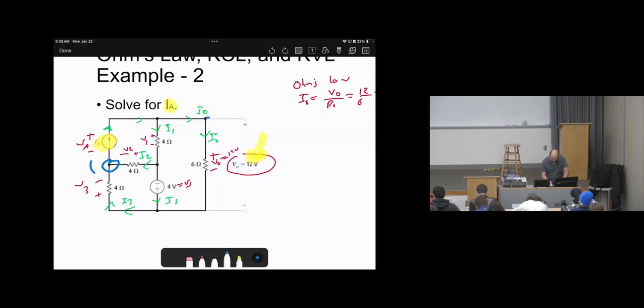Here is node 1, here is node 2. I think I messed it up. This is node 2, here is node 1. Okay. So that KVL was not a good idea. Then, how about doing KVL here? Is it a good idea? I think so, because V source is known, V1 is unknown, VO is known. So we have only one unknown. That's what I want: look for a way such that there is only one unknown. So I would say, let's do KVL at loop 1.